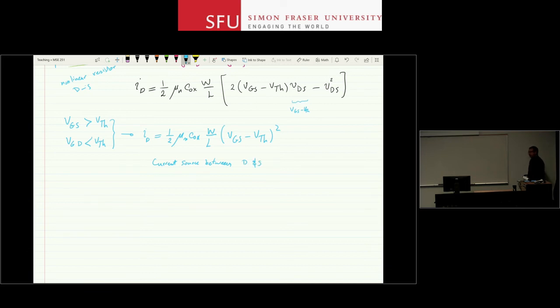Drain and source, right? Same device. I played with the gate source voltage and drain source voltage a bit. Same structure, I'm getting three different functions out of it. I have a linear resistor for small VDS values and large enough VGS. I have a nonlinear resistor if I push my VDS to slightly larger values. And I can actually get a current source out of it if I make the channel pinch off at the drain end. I can actually use the same device as a capacitor too, by extending one of those doping regions, but we're not doing that. But anyway, same structure gives you these three different functions.